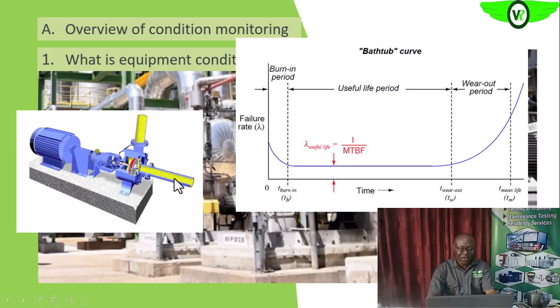All of these are indications of certain things. If the suction pressure is low, that is an indication that where the fluid is coming from is either getting low, or there are some constraints in the lines. So you see that it is worth monitoring the suction pressure.